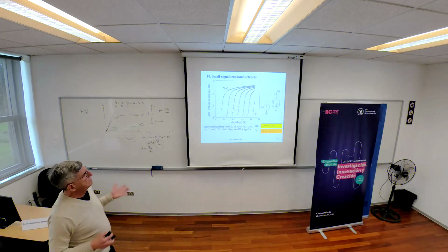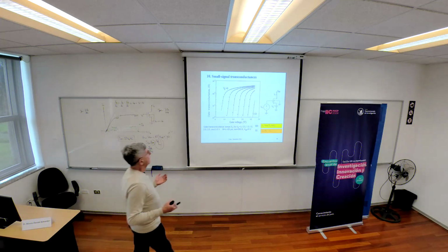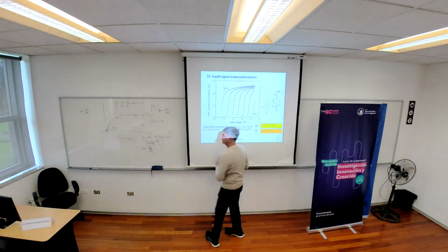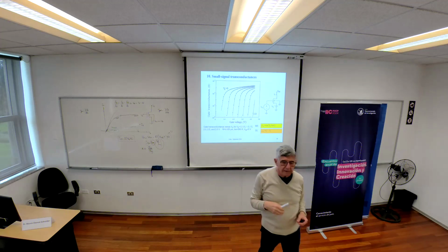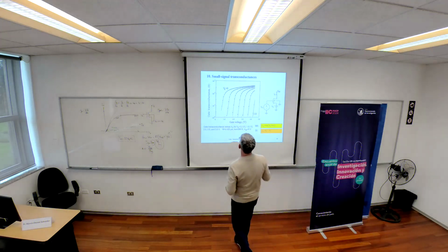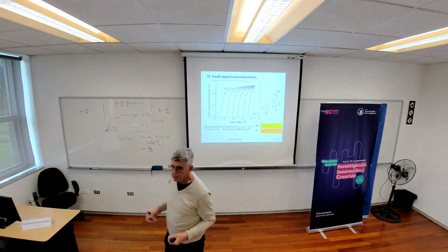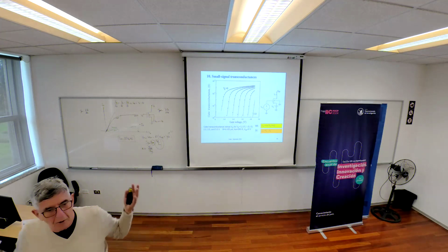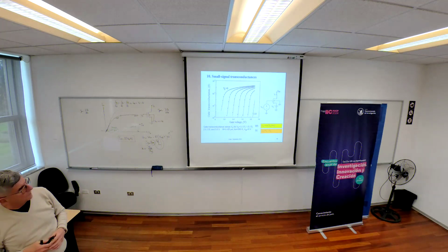Some curves here, nothing new. They give transconductance. In this region here, the weak inversion region, you have a behavior which is linear in a log scale, exactly as in the case of the current. For higher voltage, you have a modification. Of course, you have a different model. You have the square law model, and the curve changes according to this picture.